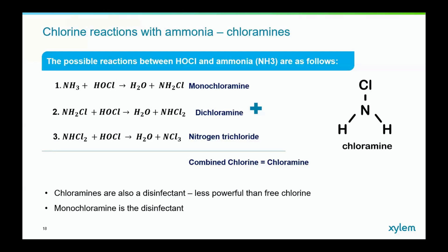Chloramines have a much lower standard reduction potential as compared to free chlorine. Hence, they have less ability to damage microbial cell walls, enzymes, and nucleic acids as quickly as chlorine. Monochloramine formation is chosen because it is a stable disinfectant. Dichloramine has some disinfectant ability, but it is unstable and irritating to the eyes and nose.